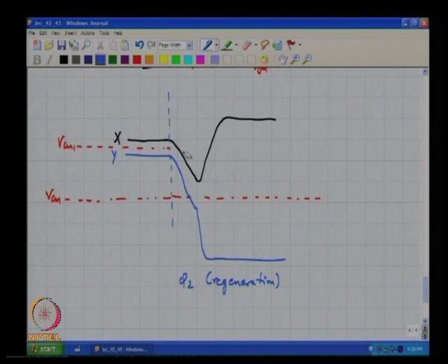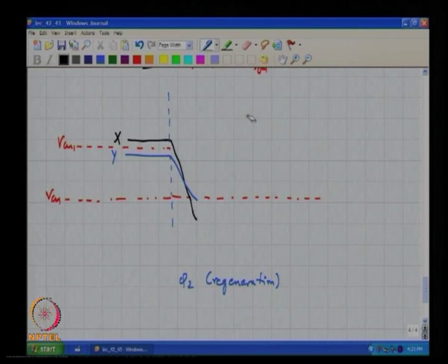So it will turn out that during this time, if the input difference is sufficiently small, what will happen is that by the time the common mode moves to the natural common mode of the inverters, which is VCM, an interaction between mismatch and nonlinear capacitance at Vx and Vy will cause the upper voltage to go below the lower voltage, and then regeneration takes over. And you get an error.